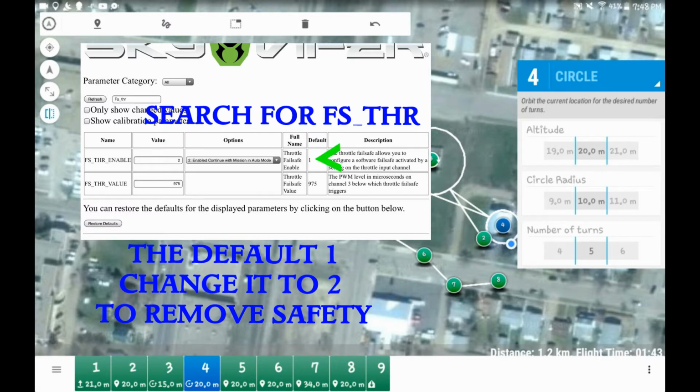Do not take off doing an auto mission until the green light is steady on. The Tower app will allow you to take off and fly the mission before the GPS lock is locked in on your remote, but do not do that. I've never tried it, but you're not safely home locked unless that solid light is green. So wait for a green lock, then send it on its mission.